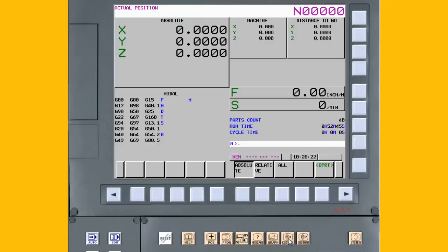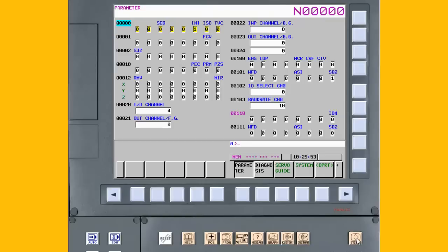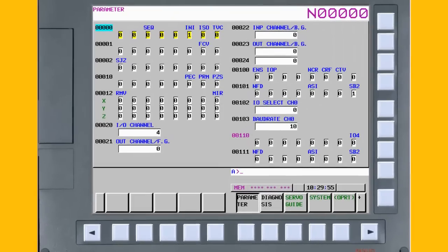To view system parameters, click the System function key. Parameters is the default page viewed when pressing the System function key, but if it is not displayed, press the parameter soft key. As discussed before, there are thousands of parameters, so it's impractical to page or cursor through that many pages. Instead, search for parameters. Enter the number 14794.